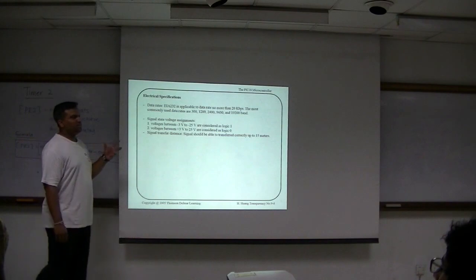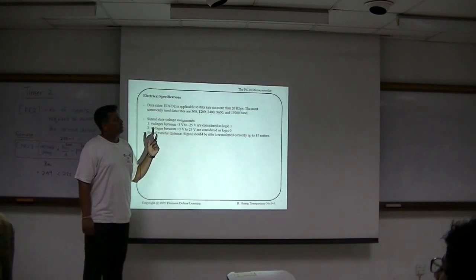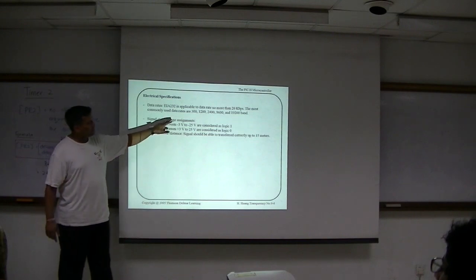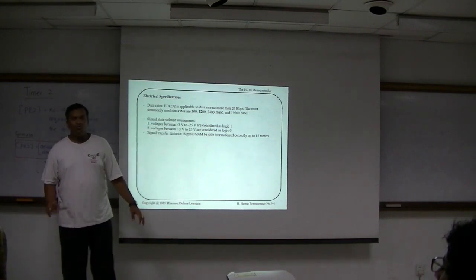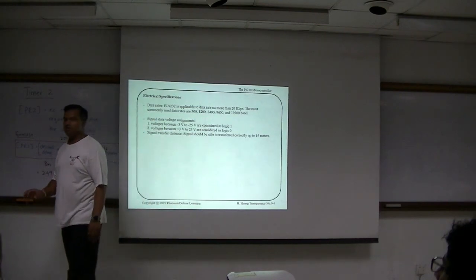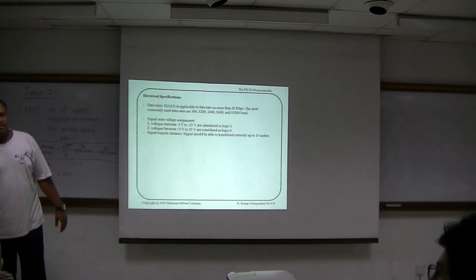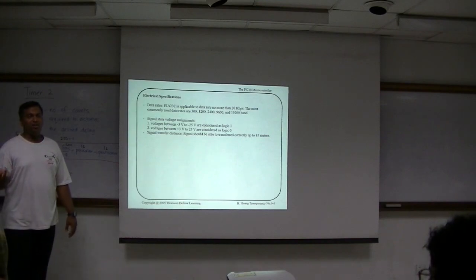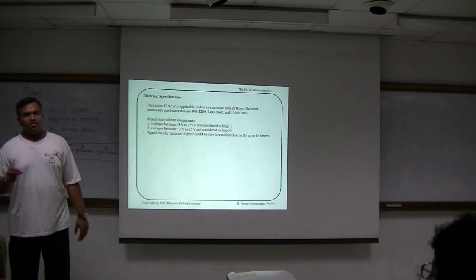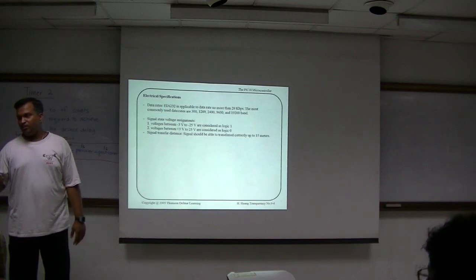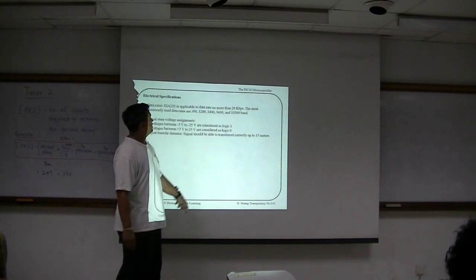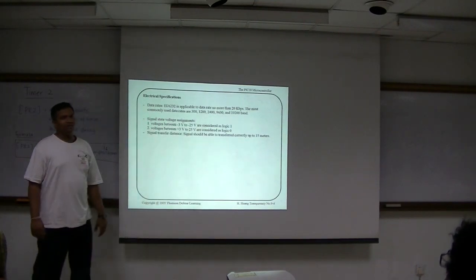The electrical specification is, one, how fast the data rates are. These are the data rates available. The most commonly used data rate is 9600 by default. Even on a PC, if you check your terminal, or download software to have a virtual serial port, you can see that the default speed is 9,600 bits per second.